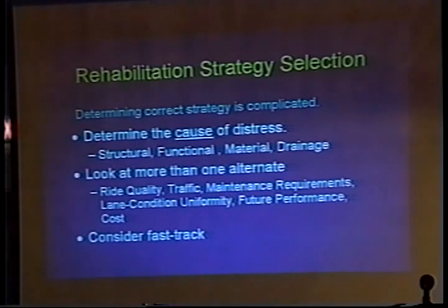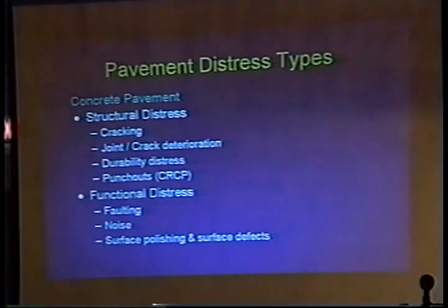They put a bonded concrete over in there. They used a maturity meter to analyze what their strength was at the time of setting and paving, so they could open that up as soon as possible without waiting for results to come back from testing labs and such. So there are some good methods and some products available to help you get a high strength gain for concrete pavements in very short periods of time, within 12-hour periods or less.